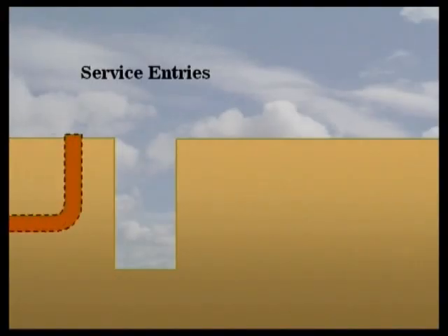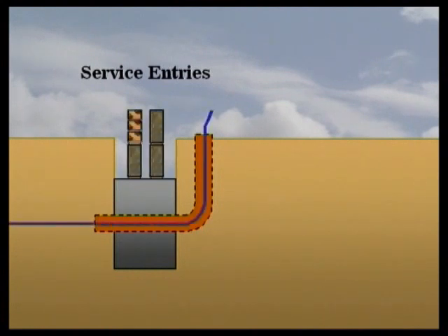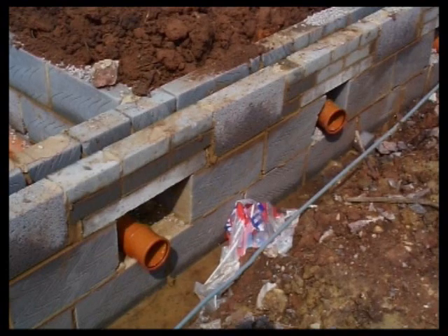A disadvantage of trench fill is that service ducts below the concrete need to be carefully planned. Mistakes can be expensive to rectify. In traditional foundations, service openings are formed in the blockwork. Their position is easy to change.